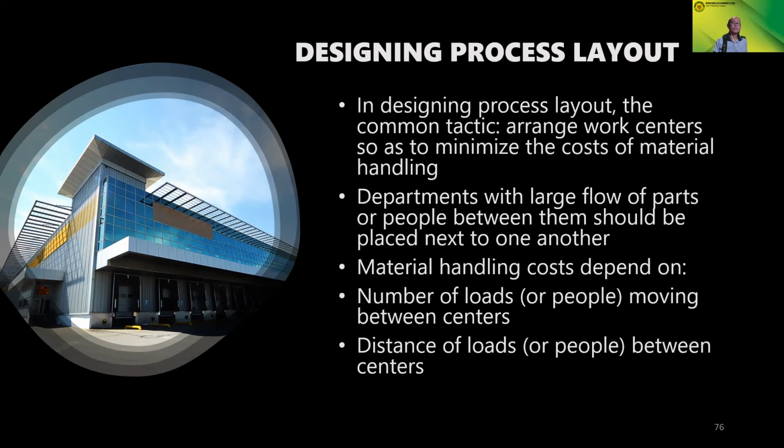The main issue in designing a process layout concerns the relative positioning of the departments involved. The problem is to develop a reasonably good layout. Some combinations will be more desirable than others. Layouts can also be influenced by external factors such as the location of entrances, loading docks, elevators, windows, and areas of reinforced flooring. Also important are noise levels, safety, and the size and locations of restrooms.